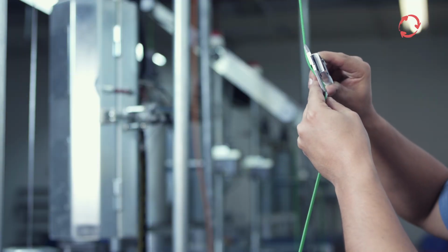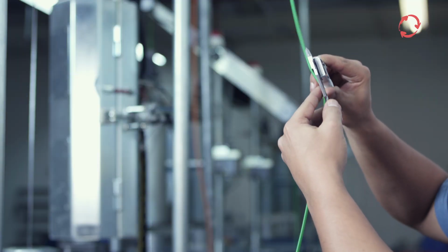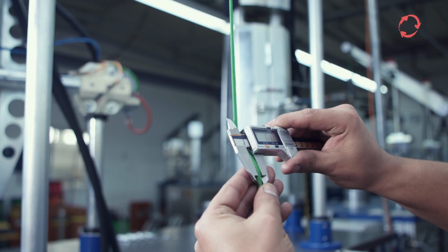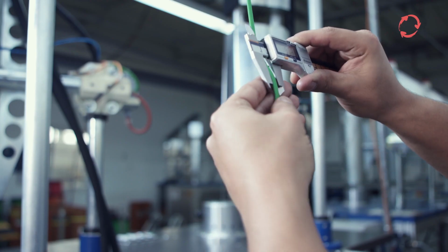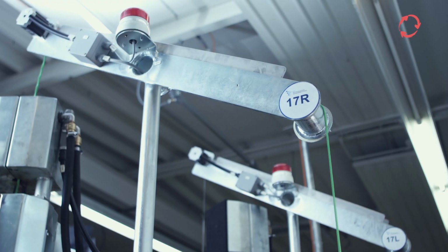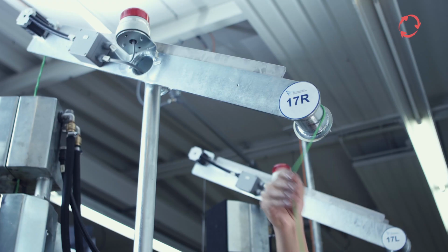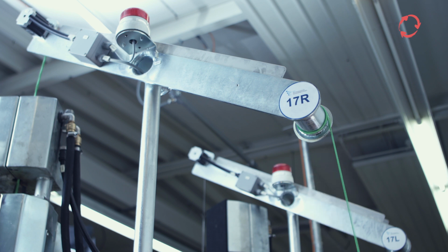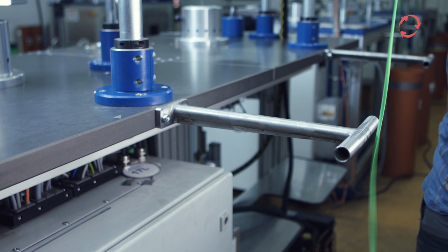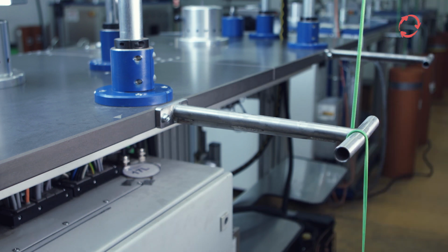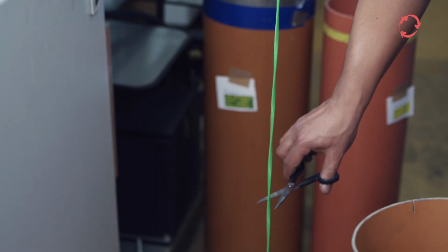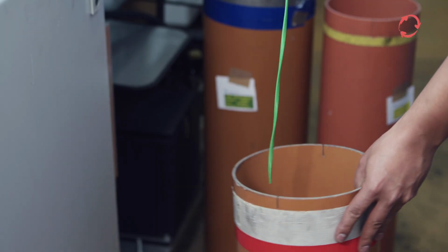The dimensions of the spirals must be regularly checked during the first few minutes of the winding process. If needed, the process parameters must be corrected. The spirals, which are wound until the desired dimensions are reached, are not suitable for sieve production. Once the desired size has been reached, the spirals are guided to the provided cans. At this point, measurements in half-hour intervals are sufficient, or 1-hour intervals if the machine is warmed up.